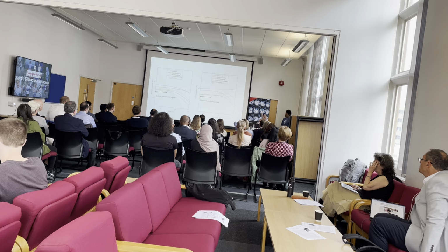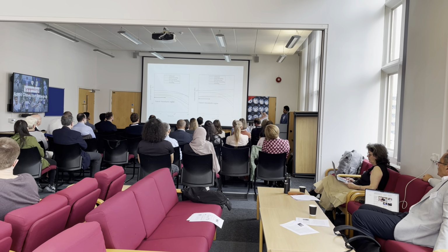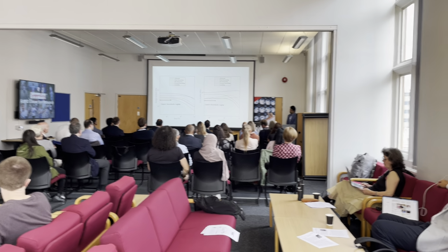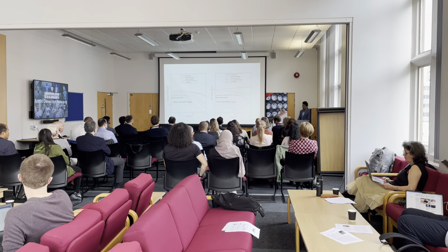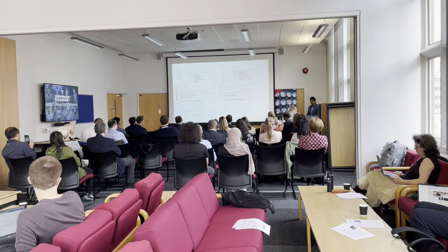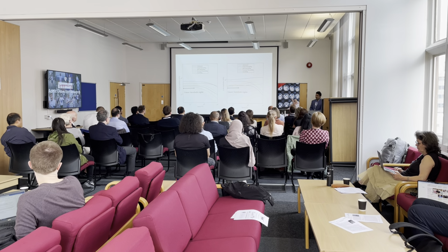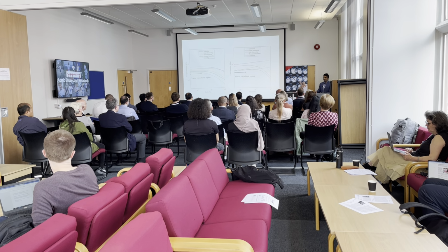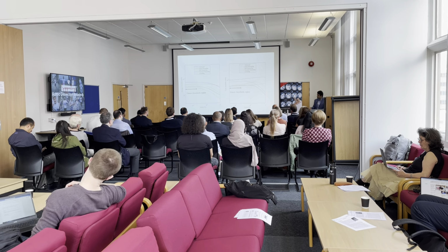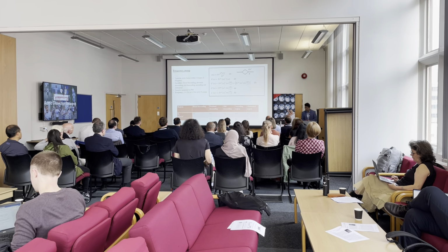So one is that we were able to see a linear viscoelastic region in all the samples, and most importantly, in all of the samples, the linear viscoelastic region extended until slightly greater than 0.1% strain, which also implies that at this particular value of strain, both the storage modulus and the loss modulus are pretty much intact. And after this, we either have a nonlinearity or we have damage caused in the samples. So this also told us one interesting thing, because once we understood the threshold limit of the shear strain, we also knew at what value of the shear strain we can perform the frequency sweep test, because I think that's the most important part, because we were fitting some of these models there.